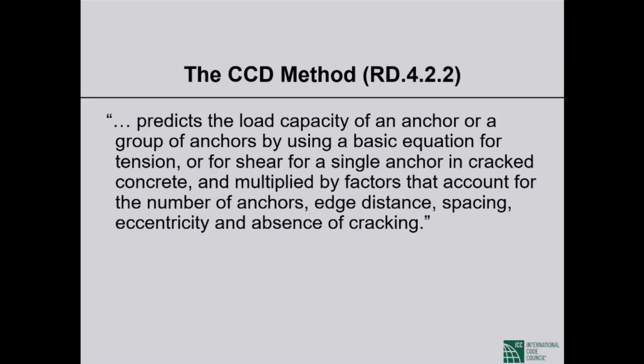Appendix K is based on the so-called concrete capacity design method, which predicts the load capacity of an anchor or a group of anchors by using a basic equation for tension, and another basic equation for shear. Each of those equations, for tension or for shear, is for a single anchor in cracked concrete.